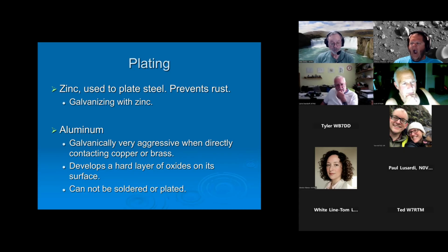So you have aluminum oxide on that surface. You can't solder to that surface, and even if you try to weld to it, if you do not clean that oxidation off, you cannot weld to it. If you're using a plasma torch to connect to it, you have to remove that oxidized layer in order to get things to stick.